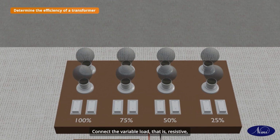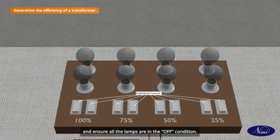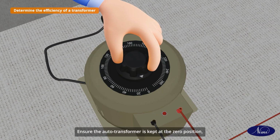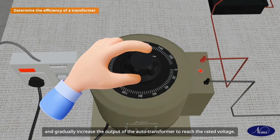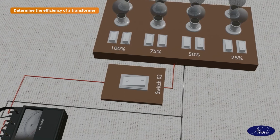Connect the variable load, that is resistive, which consists of incandescent lamps with individual control for each lamp, at the secondary side, and ensure all lamps are in off condition. Ensure the auto transformer is kept at the 0 position. Close switch S1 and gradually increase the output of the auto transformer to reach the rated voltage.